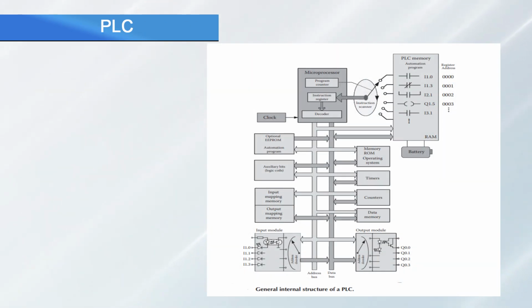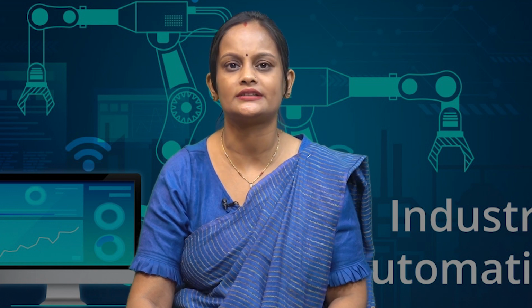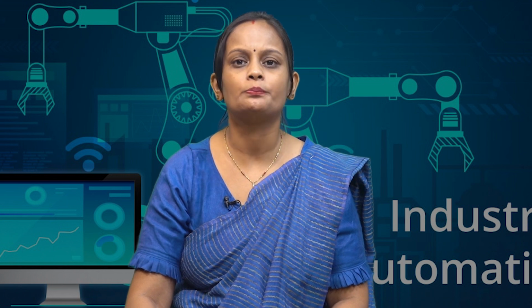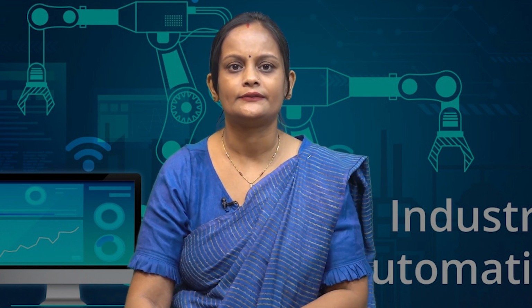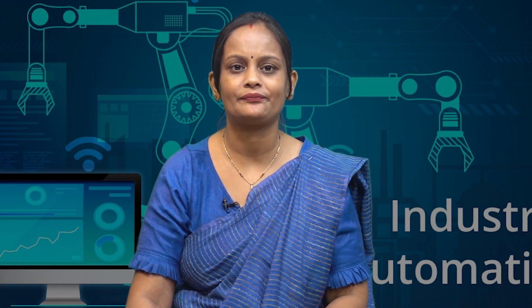Here you can see the general internal structure of a PLC. The auxiliary memory bits in the PLC function similarly to the auxiliary relays in traditional automation circuits. These single bit memory locations represent operational states and are used in automation program instructions to mimic the relay contact. This setup allows for an infinite number of contacts within the program, with each bit having a unique address.